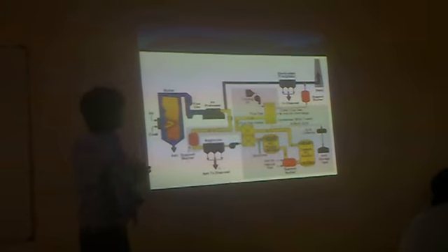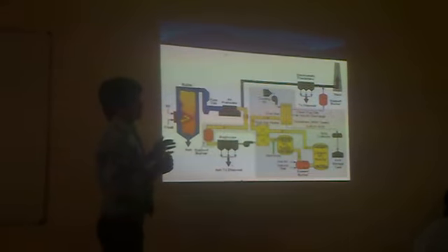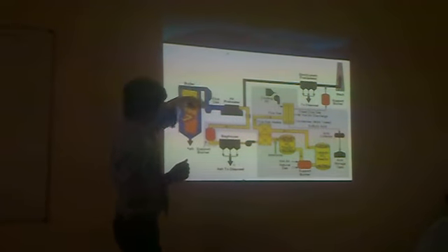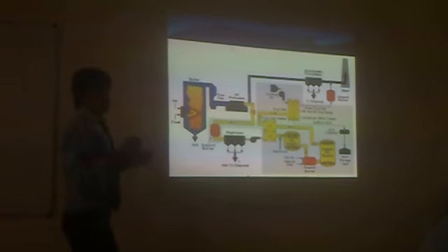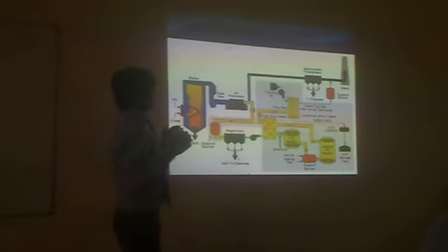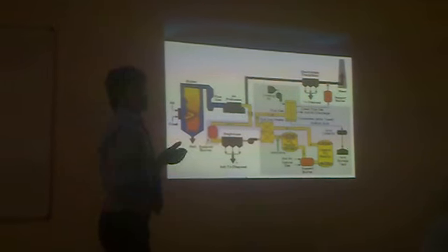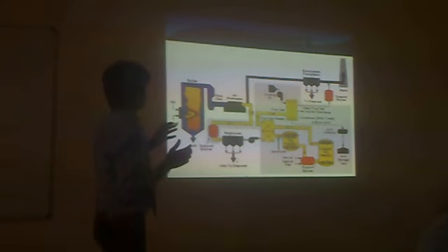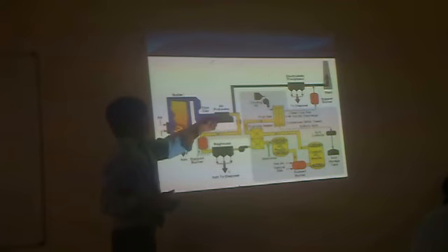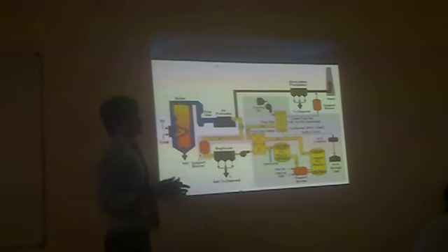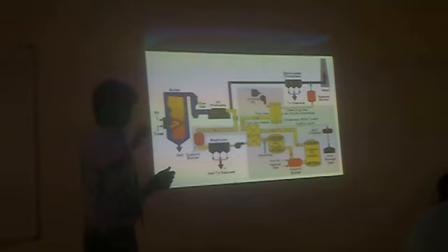There is much heat, up to 200 degrees centigrade, and this flue gas is going to the air preheater. The air preheater is also known as the air heater. Atmospheric air is about 24 to 25 degrees centigrade. Before sending this air into the boiler, the air preheater is required to heat that primary air.